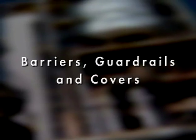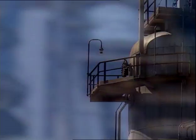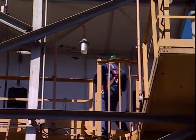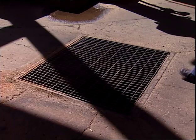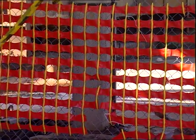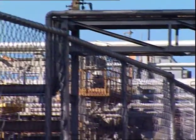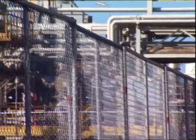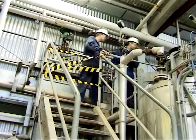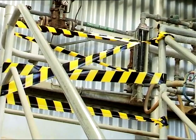The use of barriers, guardrails and covers is fairly self-explanatory, but may be a little confusing. They can be permanent or temporary and be made from a large variety of different materials and have different designs. Covers, for instance, are usually made from wood or metal, and barriers can be made from a number of different materials including rope, plastic, wood and metal. Barriers can provide a physical barrier to a working area, for example a fence, or, as in the case of a warning barrier, simply be used to indicate that hazards are present. In these situations, the barrier offers no physical protection.